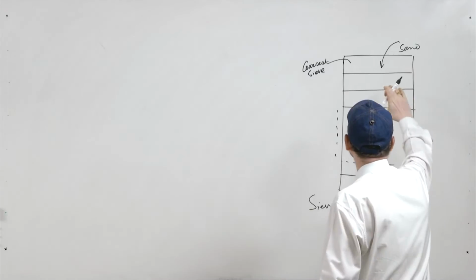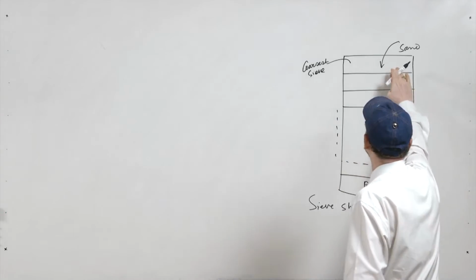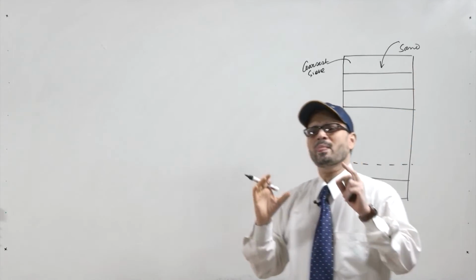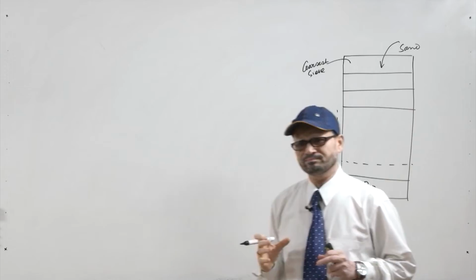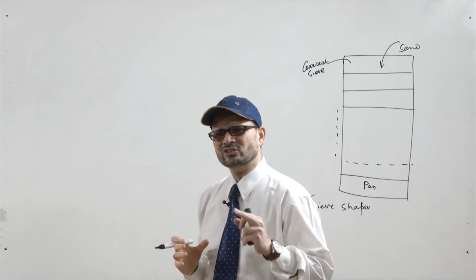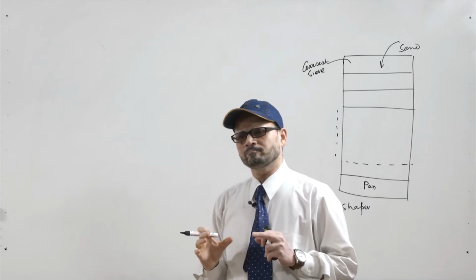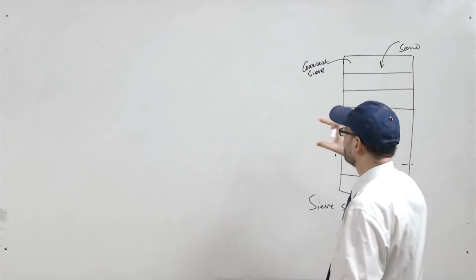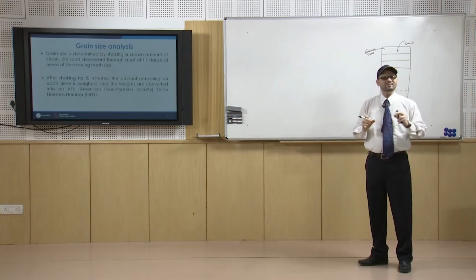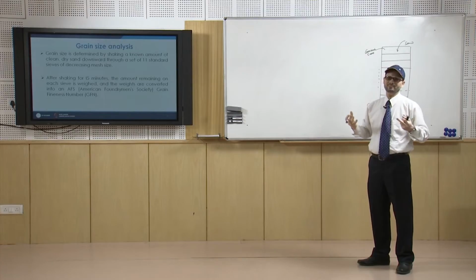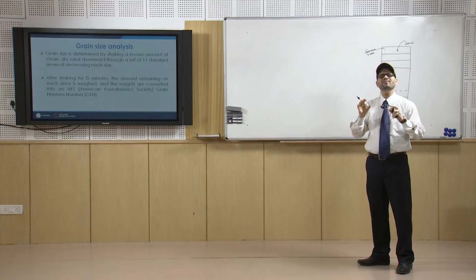From these quantities, the percentage of the quantity which is retained on each sieve is calculated. Then every sieve is given a multiplying factor. So, all these percentage quantities are multiplied with that multiplying factor, and then those products are added and divided by the total percentage. The total percentage will certainly be close to 100. So, that divided by nearly 100 gives you the grain fineness number.